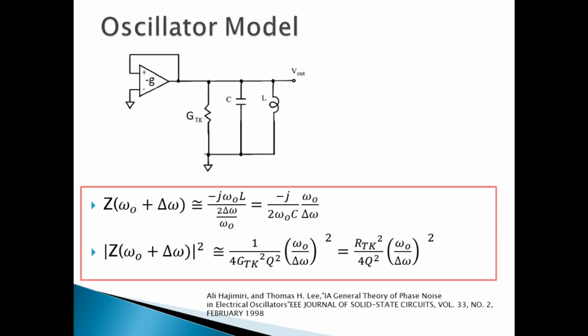So any harmonic oscillator, especially those that are based on a resonator that is being undamped, can be configured as the following with an LC tank. The tank conductance GTK. In order to keep the oscillator going, there should be an undamping circuit, essentially minus G, that is the negative resistance. It must be greater than GTK. As soon as that condition is fulfilled, this circuit will oscillate.